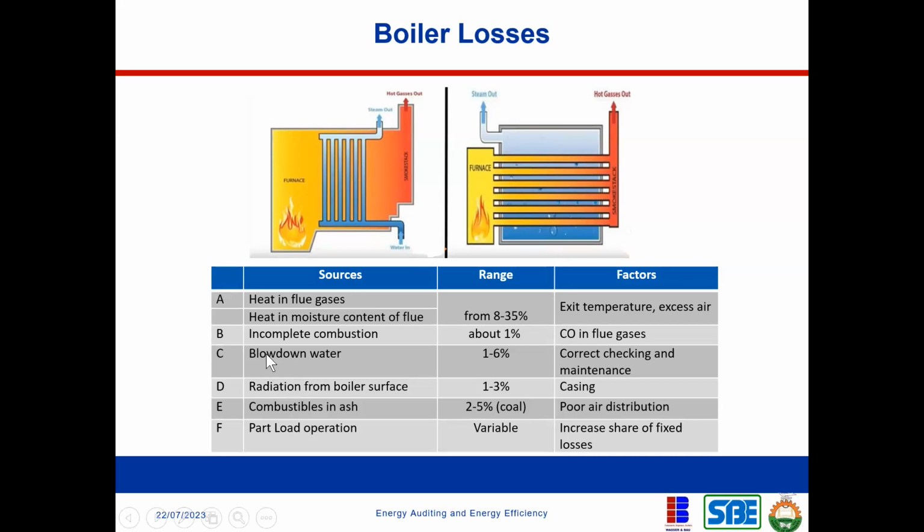Okay, you know that when you heat water and water evaporates, sometimes if there are impurities in the water, you will see scales on the surface. So assuming you put 1 liter of water in a kettle and you have impurities in that water and you heat that water, once the water evaporates and turns to steam, sometimes you notice there are scales. All those impurities will settle at the bottom of the kettle, right? So it affects boilers. When you keep adding water to boilers and evaporating them, they always have solid residues. We call them total dissolved solids. They begin to form inside that boiler.